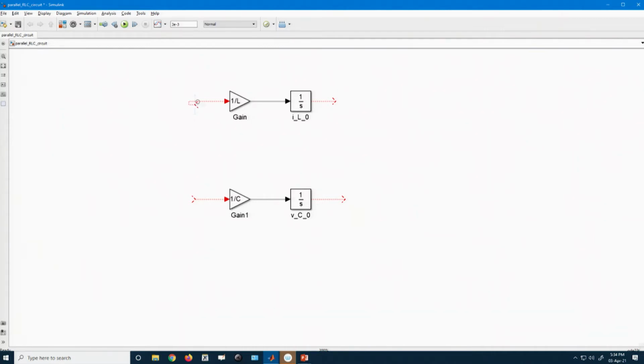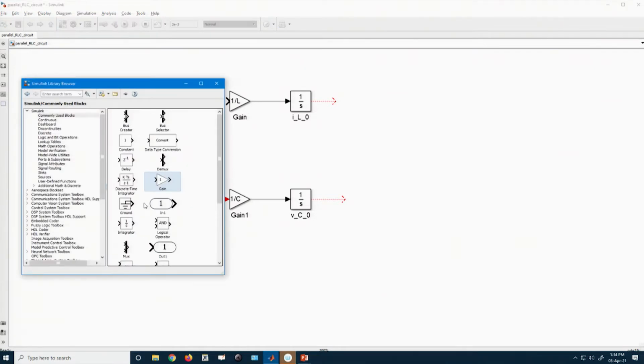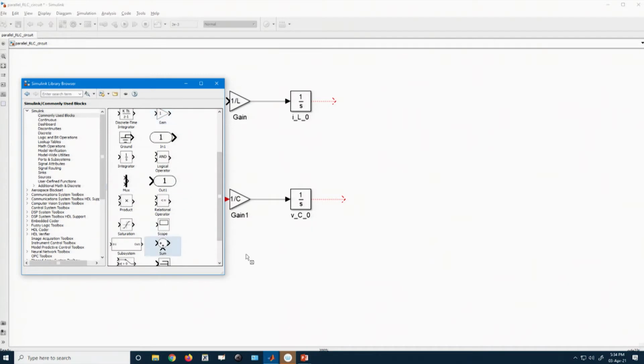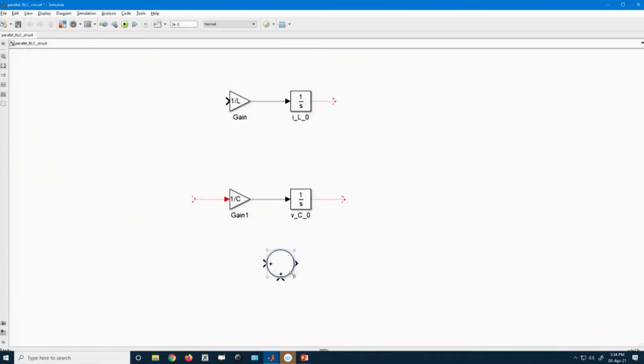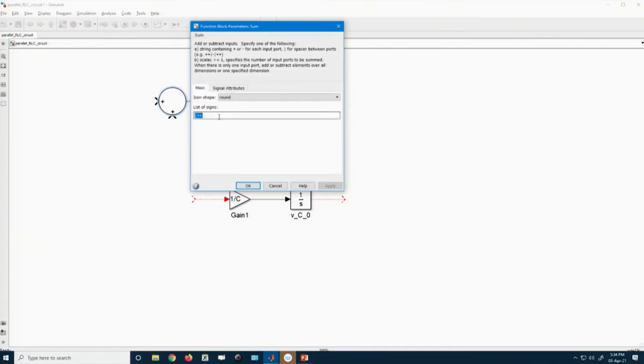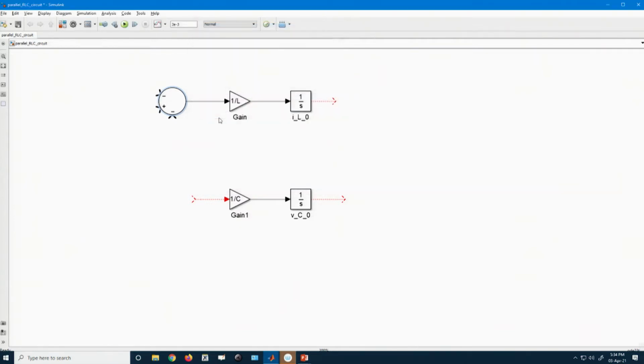That means now we need to connect this summing block. So, in this summing block we need 2 subtractions and 1 addition. So, the first subtraction will be the IL RL drop. Okay. So, that means we need another block here, just a minute.